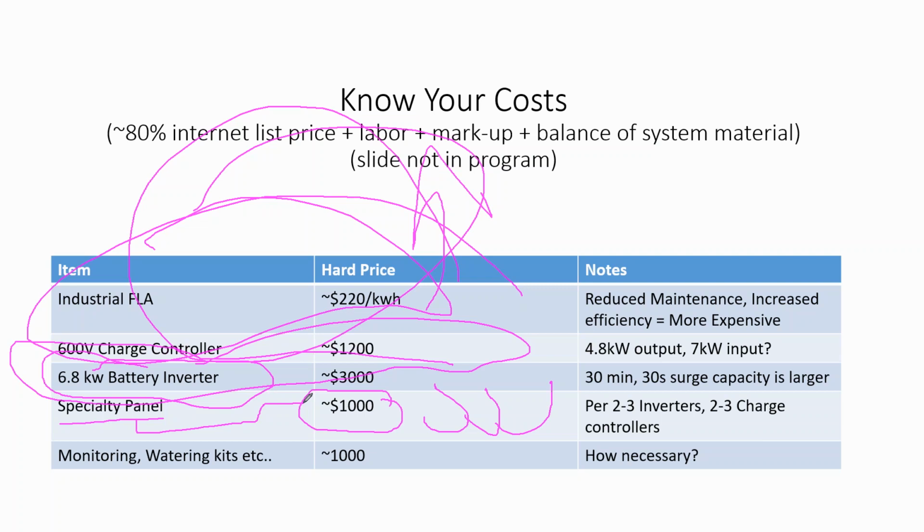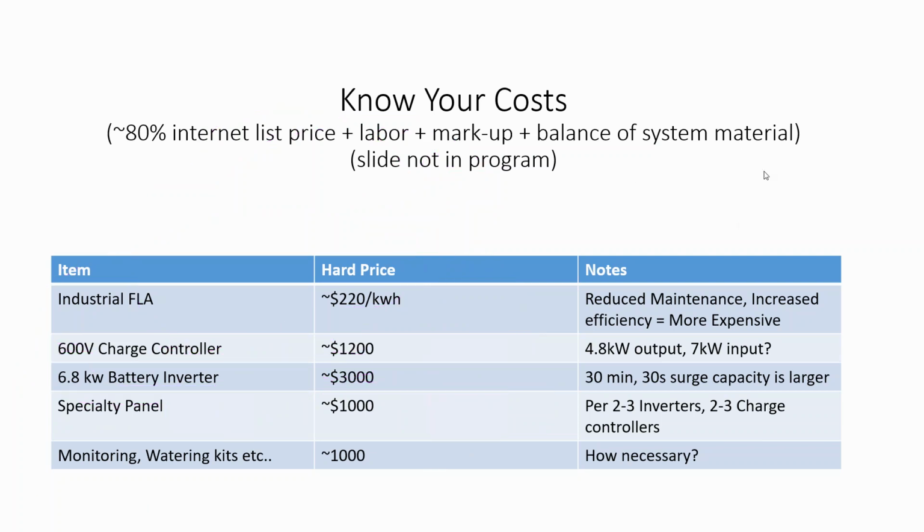So you can take, up to 10, and that's just a number pulled out of my head, but a lot of these battery inverters are scalable up to 100 kilowatts before you get into central battery inverters. And so not all of these prices are just going to scale up in terms of dollars per watt. You really need to have a more specific mindset of designing your battery capacity or your inverter output capacity based on your hard measured interval data.